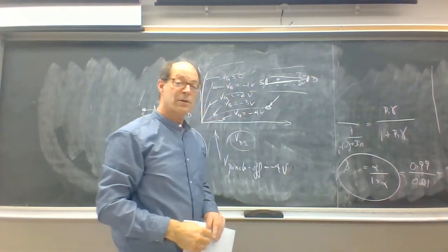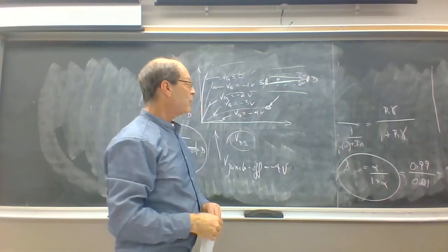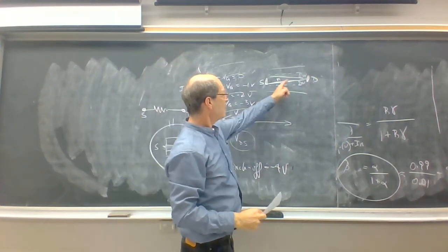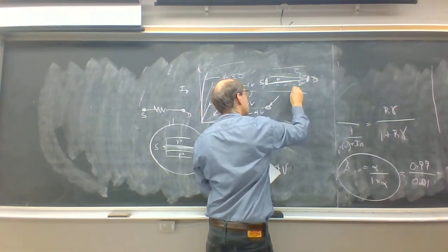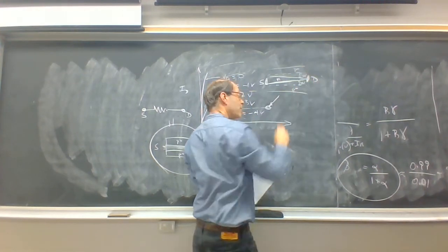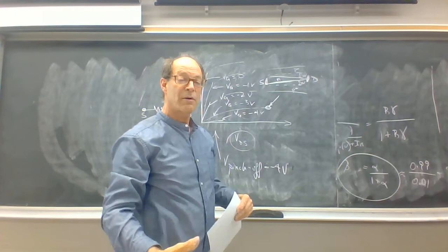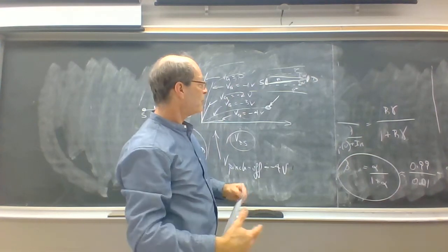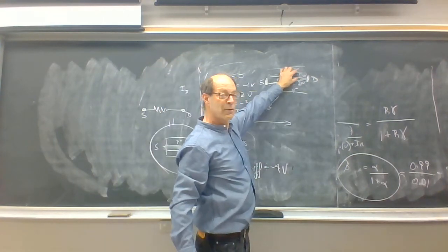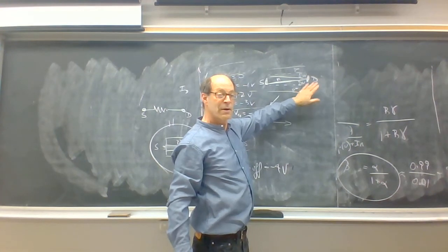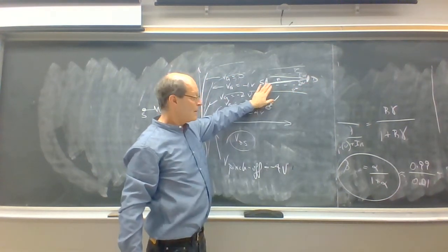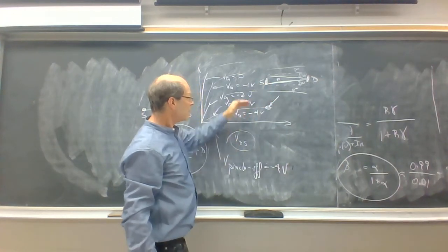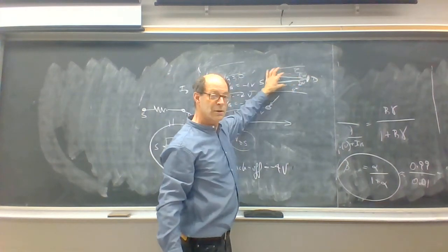As the drain voltage goes more positive, the reverse bias across the NP plus region becomes higher. You get a stronger reverse bias. The stronger reverse bias means that the widths of the depletion region on this side are higher than the widths of the depletion regions on this side, which means that the channel is shaped like a wedge.